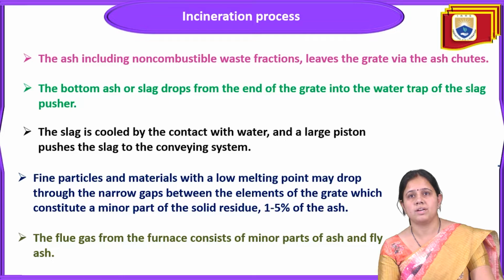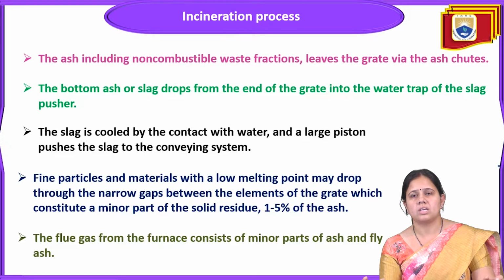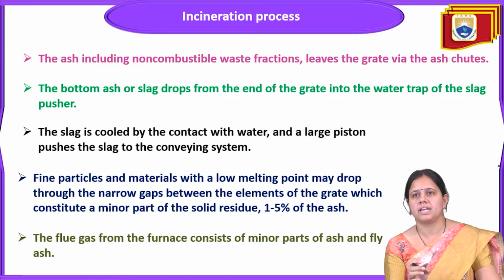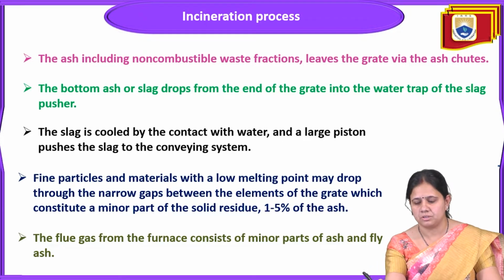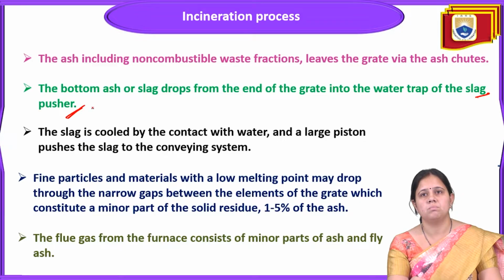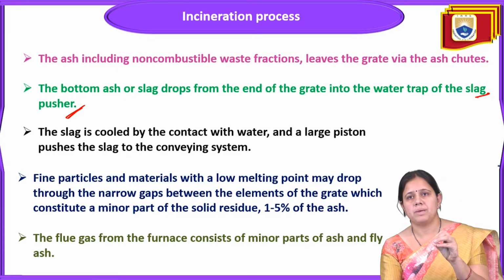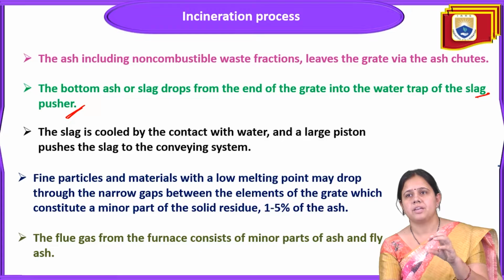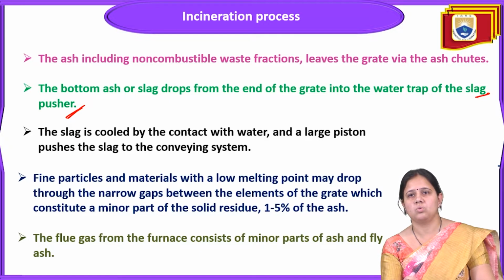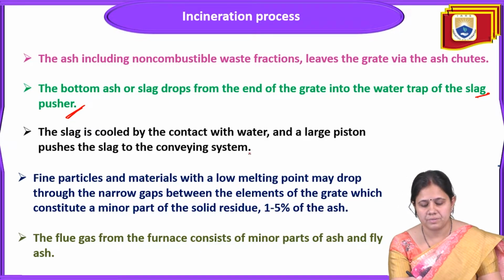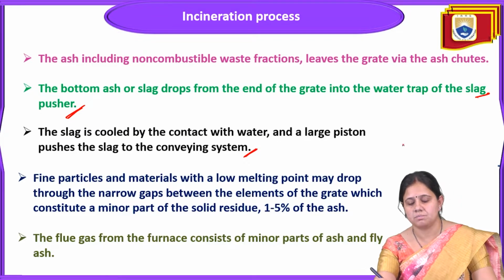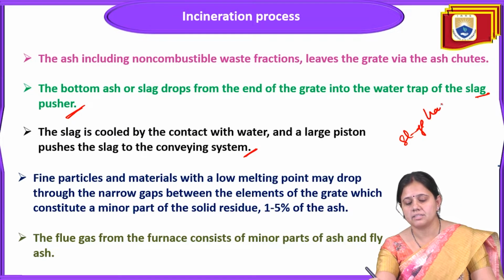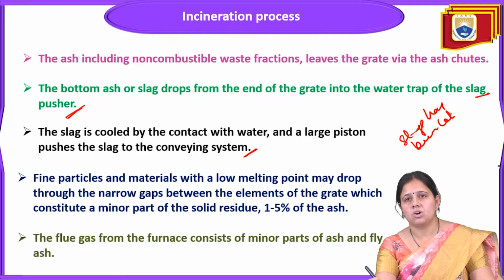Next point is what happens in this incineration process. The ash, which is the non-combustible waste fraction, leaves the grate via the ash chutes, and the bottom ash or slag drops from the end of the grate into the water trap of the slag pusher. The slag is cooled by contact with water.